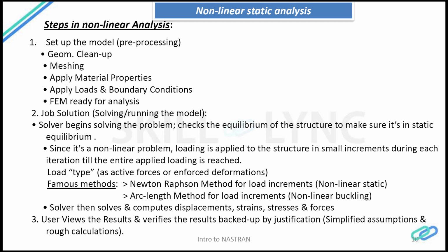First it will apply 10 newtons, and then it will solve the problem and extract the forces. Then in the second iteration, it's like a loop, it will go back and apply another 10. So 10 and 10, the existing 10 will become 20. Now it will solve and go back to the loop again where the load is applied, and it will apply another 10, which becomes 30. Similarly, the loops run until the maximum specified load is reached.